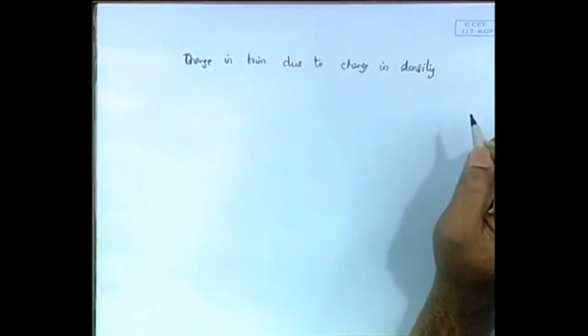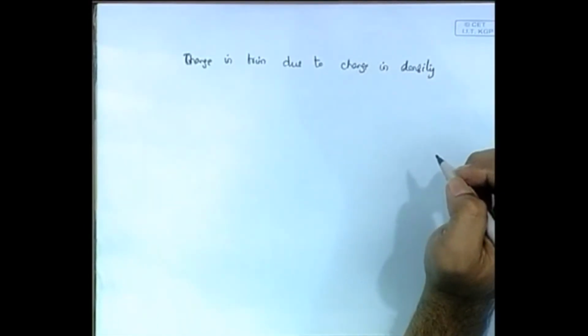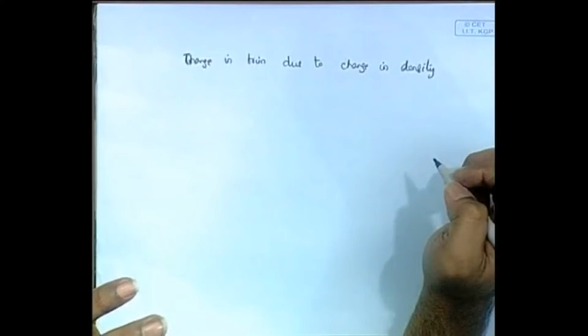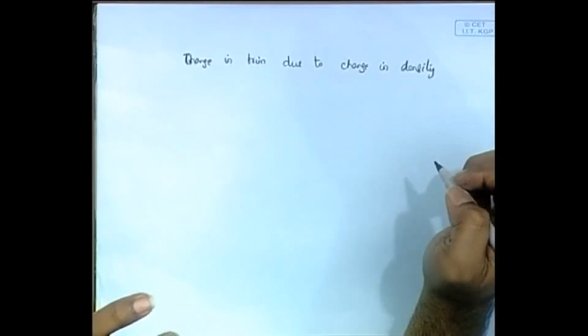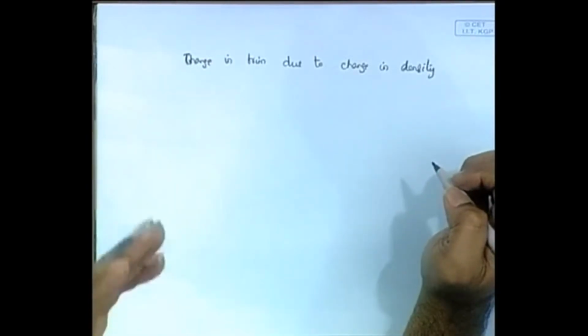Now, suppose that a vessel moves from water of density rho 0 into another water of density rho 1. For instance, a ship that is traveling moves from some kind of lake before it reaches the sea, and then it moves into the ocean. So it produces a sharp change in density, and when such a change in density occurs, what will happen? First of all, a parallel sinkage will occur.